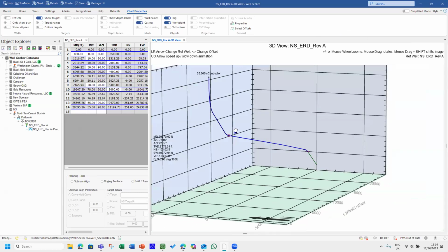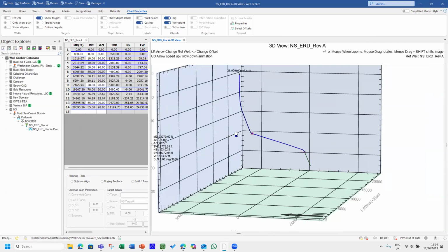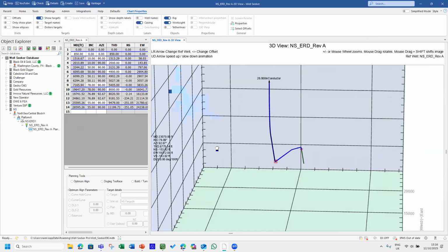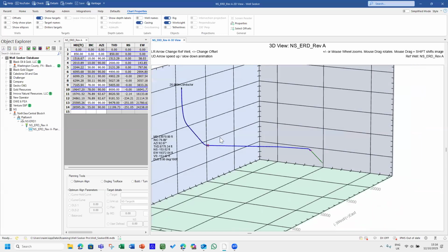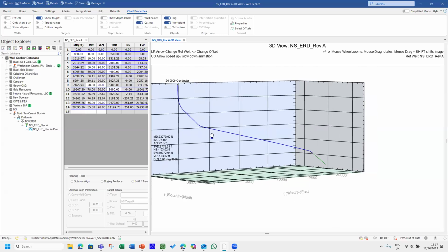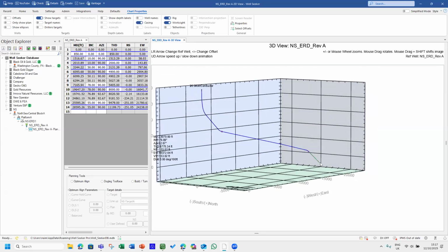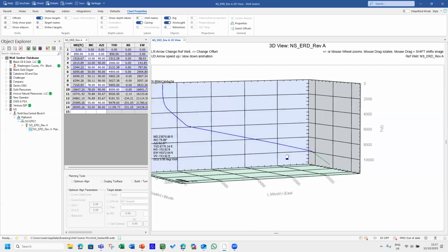And not just hydraulics and torque and drag, because of casing wear. They have these surge and swab, torque. Torque is a massive problem. Which section do you think will be a killer? The killer will be the long tangent because of the torque. Okay. There could be some more at the bottom. The very bottom sections are the most demanding for technical limits.